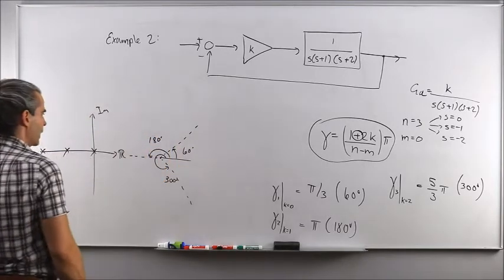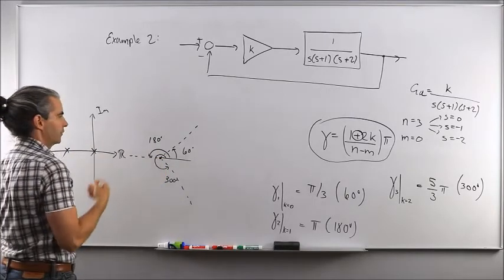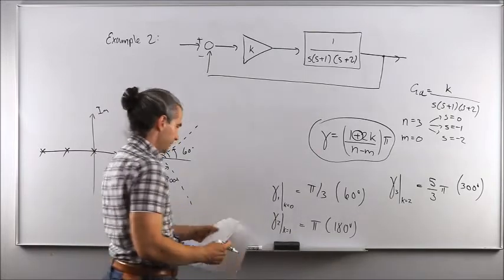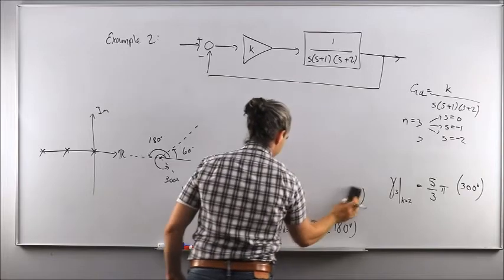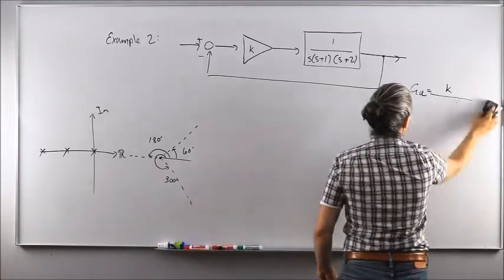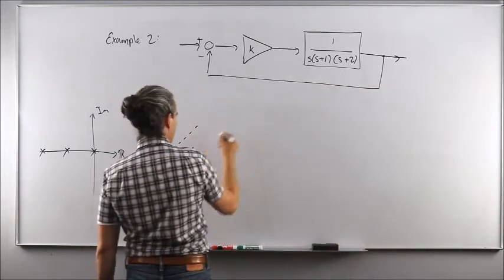Like that. I don't know where this point is along the real axis. I'll figure this out in this very next step, in step 5. Step 5 is all about the intersection of my 3 asymptotes with the real axis.